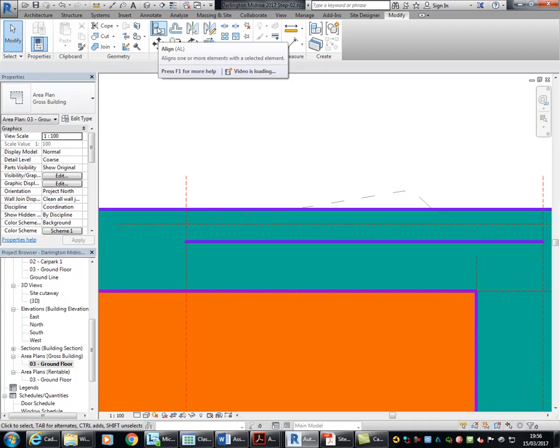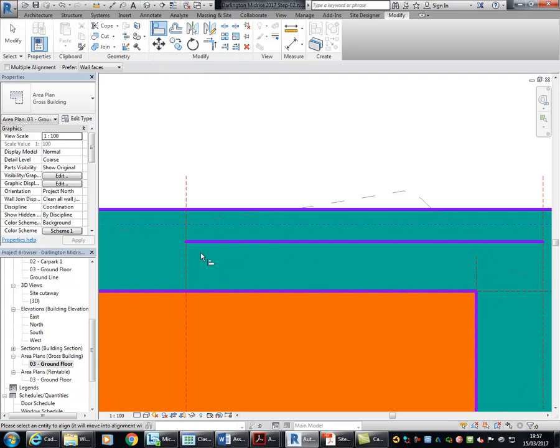So when you click on align, you pick the object you're going to align with first, then the thing you want to align with it or line up with that object. And then it will always give you the lock option. So people doing a lot of this work, setting constraints and things like that, will use the align tool constantly throughout the day. So I can lock that.